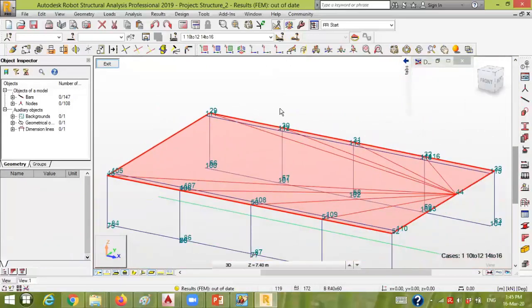We have now the elements resting on the corbels, acting like a ledge beam. And then between this ledge beam, we have to place our double T beams. It's a system of precast elements.